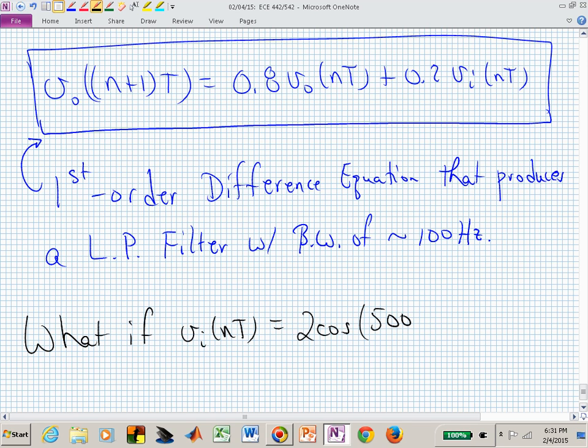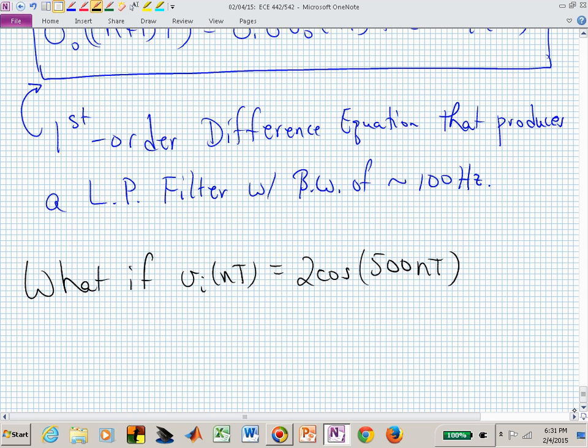So now we're replacing this little t, which is a continuous variable, with a sampled set of points on the time axis. T, capital T, we've already picked. That's that 0.000333. If we multiply that out, we have cosine of 500 times T, which is 0.1665 n.